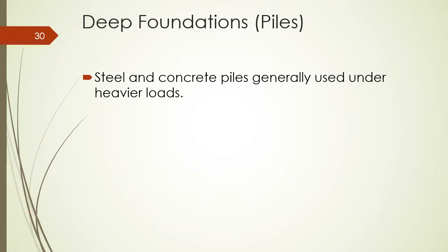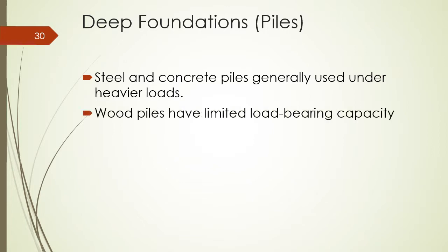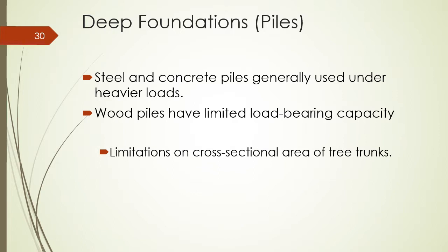Usually I'm going to have steel and concrete under heavier loads. Wood piles have limited load-bearing capacity, basically because of the nature of the material, and limitations on the cross-sectional areas of the tree trunks. I can only get a wood pile of a particular size because there are fewer big trees out there.